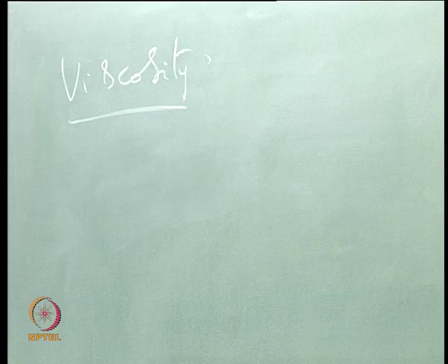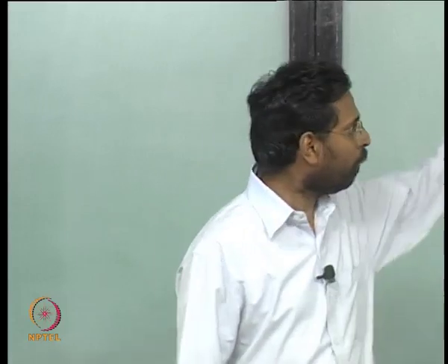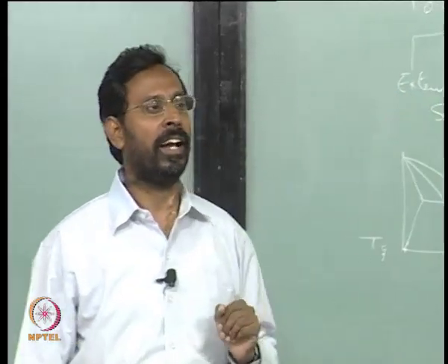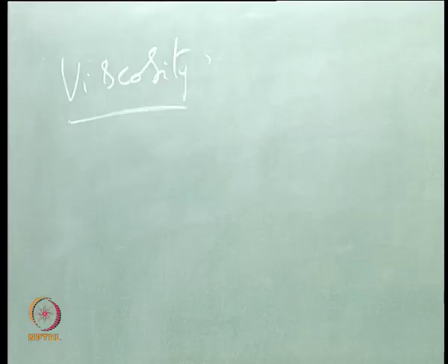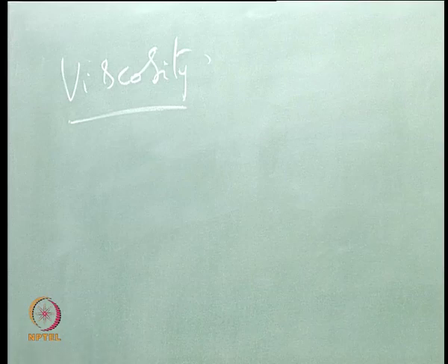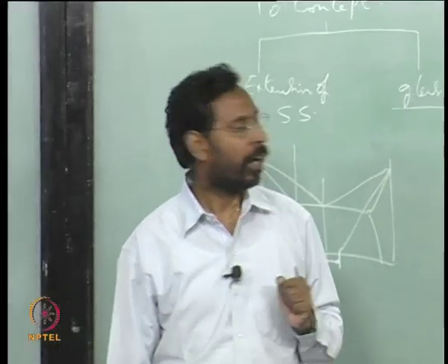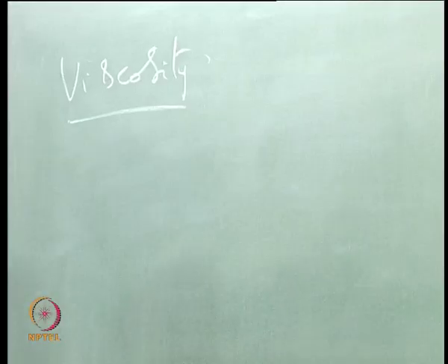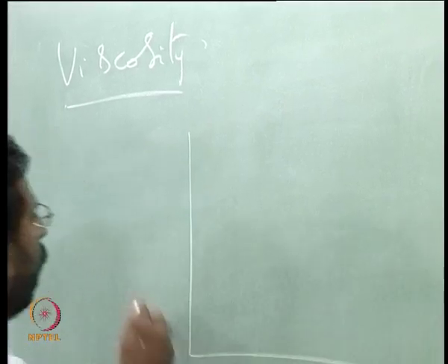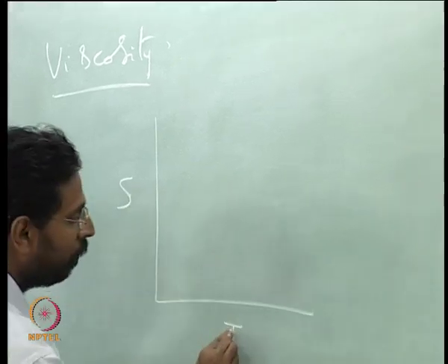Now let us try to understand this glass formation from the thermodynamic point of view. What we have seen with viscosity is mostly a kinetic point of view, and now we look at it from thermodynamics. How do we understand glass formation? Glass formation we understand from the entropy criterion, if I look at how the entropy changes as a function of temperature.